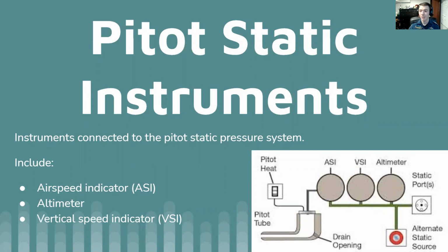As I'm sure you know by now, there's a reason they're taken from different locations. The ram air is needed for the pitot tube to find out how fast the air is entering and what that pressure change is. The static port is supposed to take as close to an ambient reading as possible. So if you weren't moving, if you were just floating there in the air, what's the temperature and the ambient pressure of the air at that point? Obviously, you can't get exact readings, but you'd be surprised at how good the static ports can be, in a general ballpark.